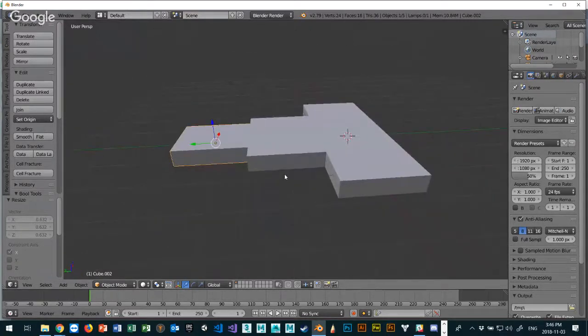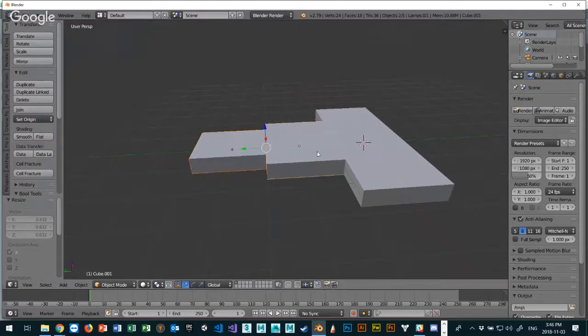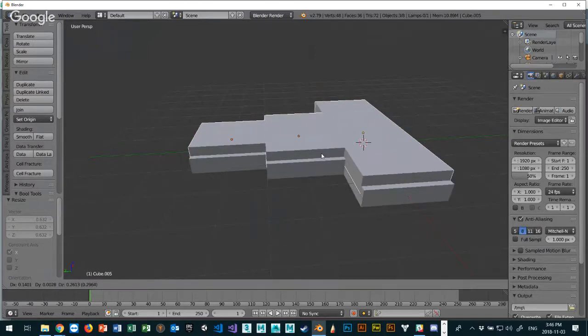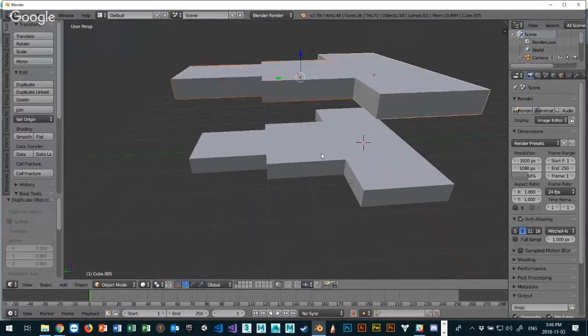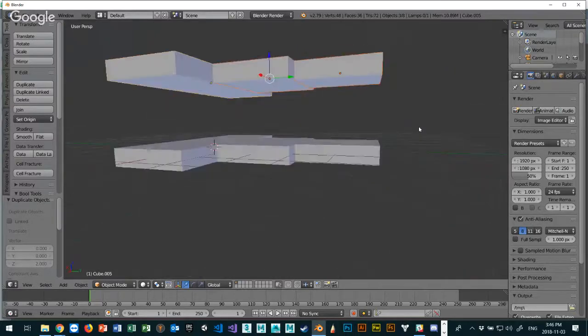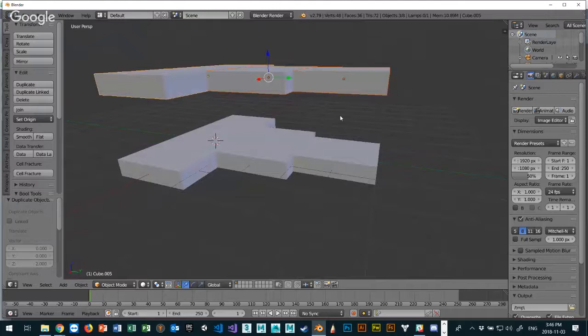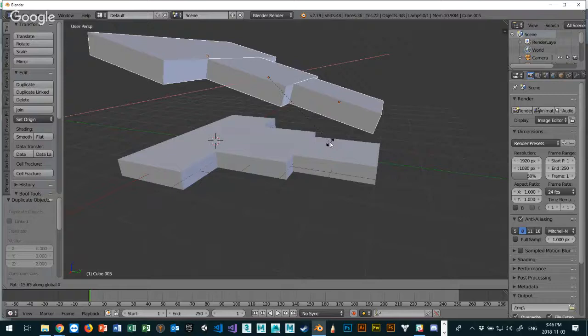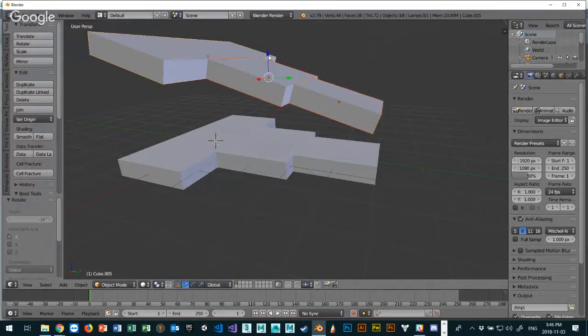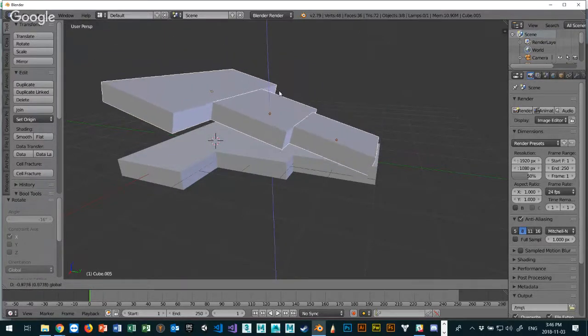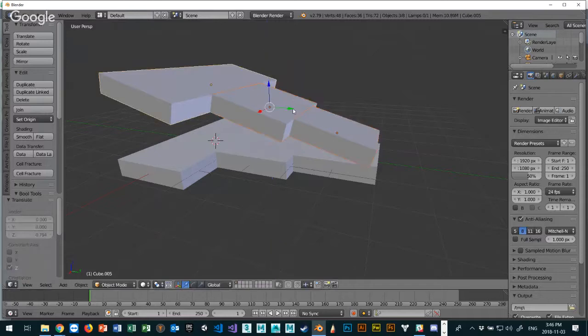And then I can start duplicating. I can Shift right-click on all these objects and press Shift D. I can duplicate this across the z-axis, 2 units. So there's my 2 units. So I can see that I have objects that are looking like this, right? And then I can rotate across the x-axis until I have what I want. And then I can use my manipulator arm to pull these objects together until I have the look and feel of what my spaceship is going to look like.